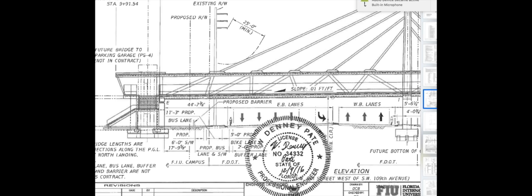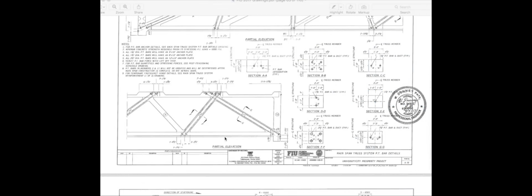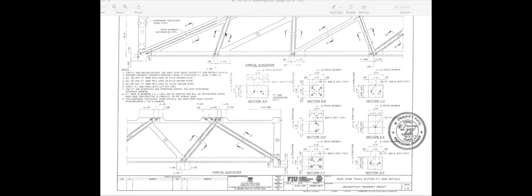All right, I'm going to continue this video. Center span, I believe the lower deck started deflecting downward. The actual top canopy did not deflect downward; it had more integrity than the lower deck as far as deflection goes. That pulling downwards created this tension in here. Even though the engineer says that they post-tension number 11 and number 2 up here, and I'll give you more on it, that post-tension created tension in here that opened up 4 cracks in this one and 2 in this one.